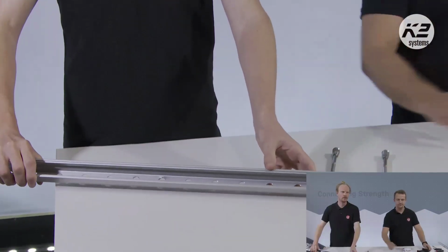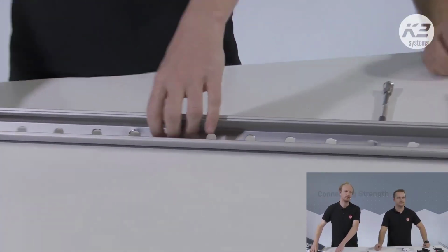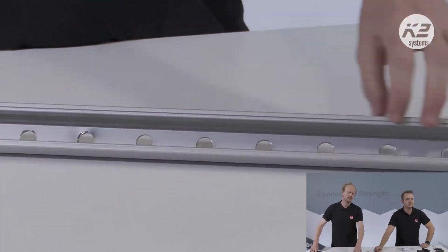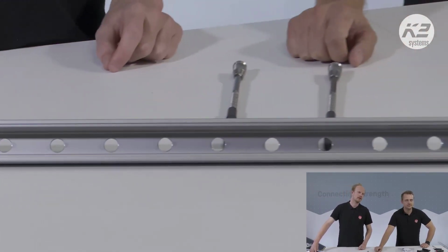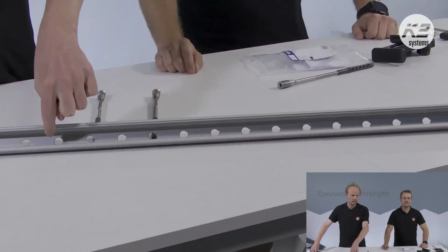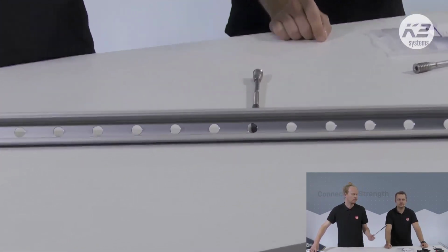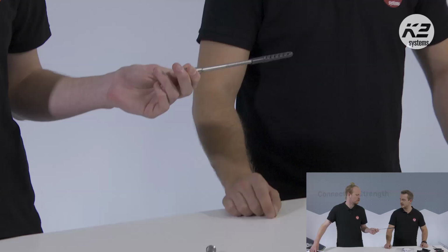Yeah, super. So here I have a full-size piece of rail that we have, but I'll maybe move it over. It is our multi-rail channel. It's just a lot longer version with perforations as well. So these will come preset. The rail will come in, I think, a 4.2 meter length, and the M10 or roughly 13 mil holes are suitable for these Reißer screws.